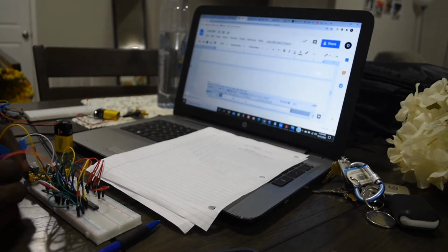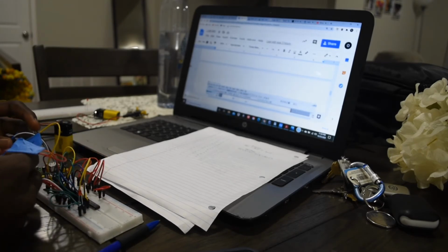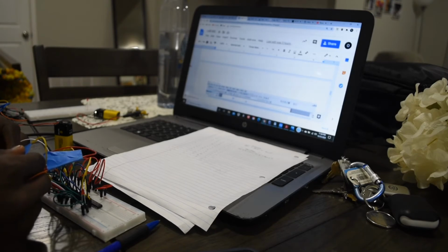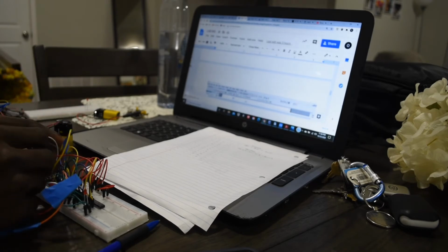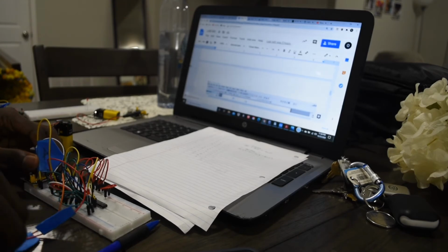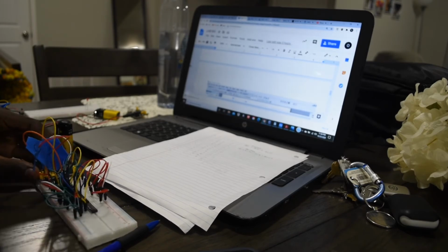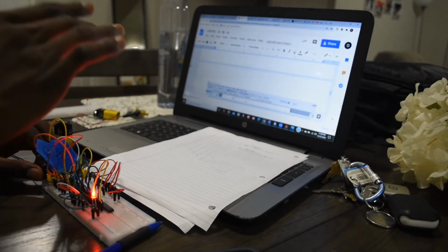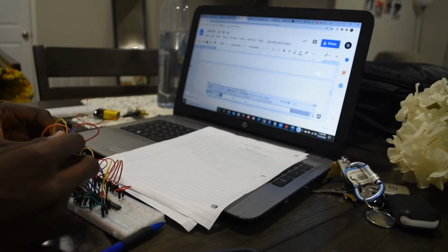I'm going to do about 3 to 4 or 5 to prove that this circuit is correct, and it's the same with the mini terms. So we have A is 0, B is 0, C is 0, D is 0. So what we should expect is that the lights should come on. Anything other than that means it is wrong. So the lights came on because that is when A, B, C, and D is 0, the output will be 1.